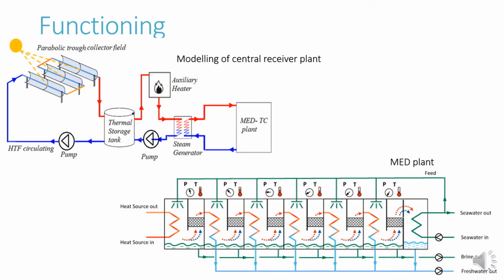Part of the seawater used to cool the condensers is rejected and the rest is the feedwater required to spray the cell 1 top bundle. The fresh water is extracted from the condenser by means of the distilled water pump.